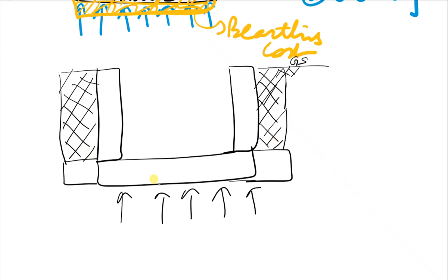Because of this, the volume of concrete required in design is only what is sufficient to arrest the crack width and to counter the moments. So only that much required thickness of the raft will be provided, which is sufficient for the crack width limitations and for the reinforcement requirement as per the moments induced in the raft.